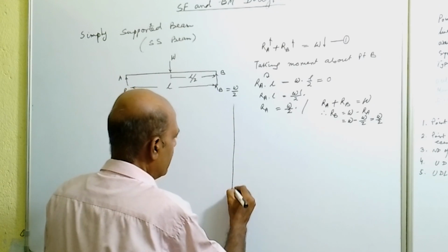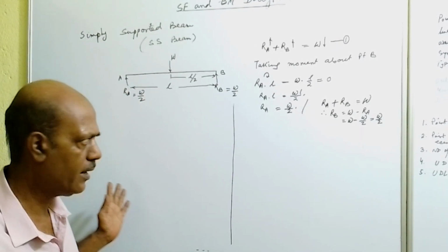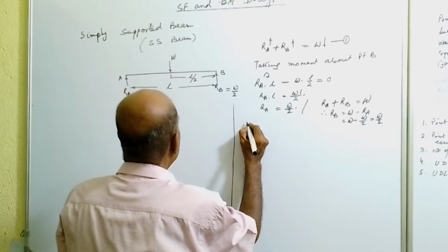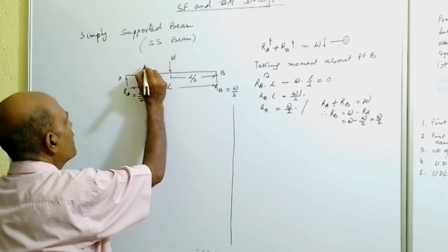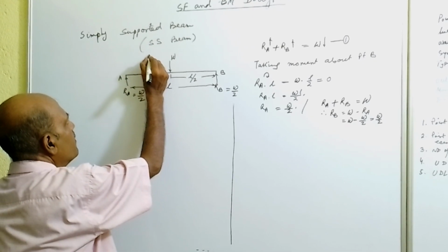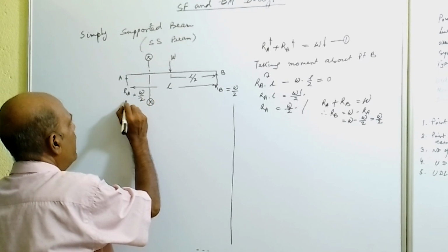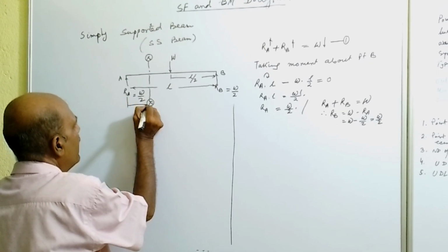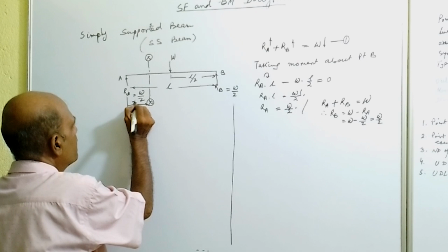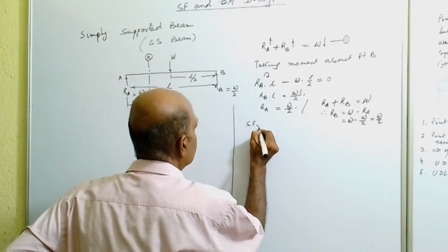Now for drawing the shear force and bending moment diagram, we will do the calculation on the right side of the page, and on the left side we will draw the diagram. For shear force calculation, consider a section XX at a distance x from the left end. Now, the shear force at XX.